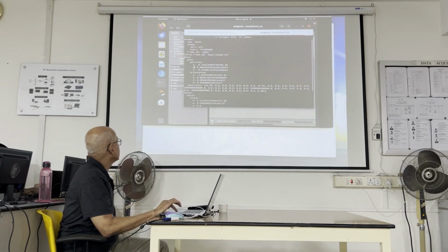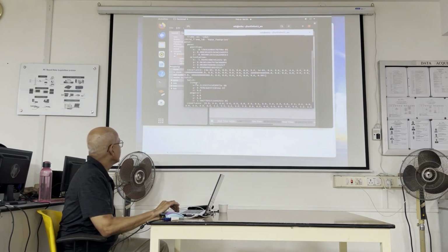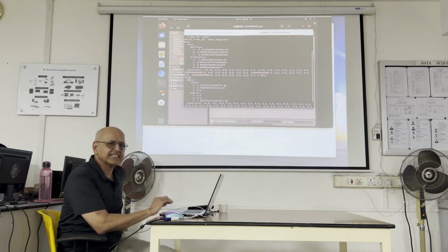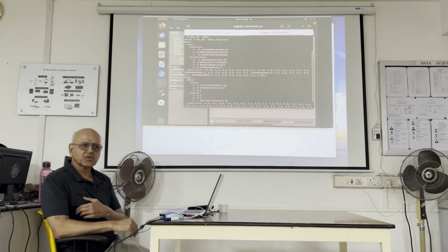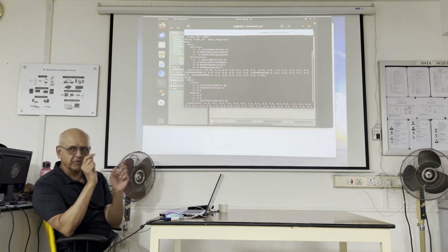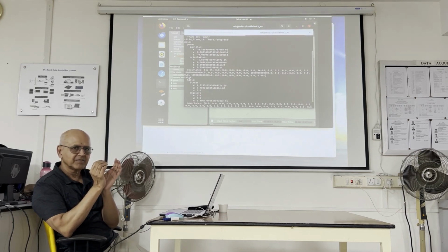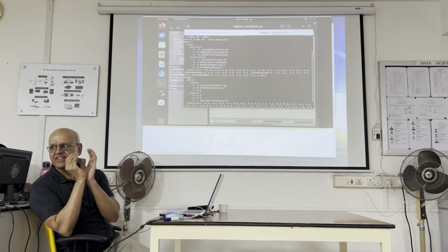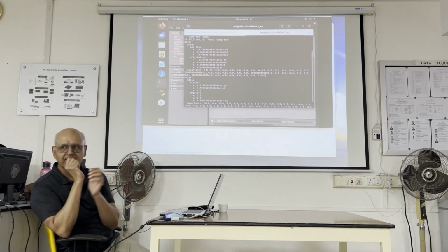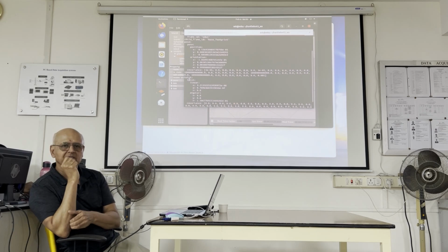Okay, now, don't worry about the covariance, but I think we should look at this part. Twist is the name given by the robotics guys to this pair of commands, V and omega. Remember I said that robots are commanded by a V and omega pair? That is called the twist command. So when you say twist command, you mean a V and omega. That's how you typically command robots.